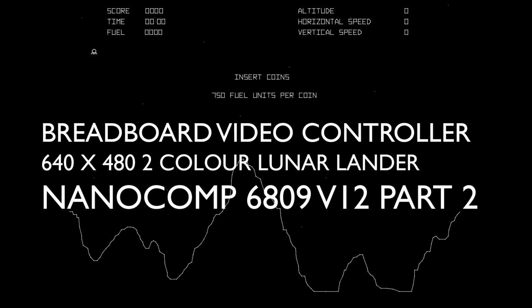I've got an analog joystick which I'd like to use for controlling the lander. The keys aren't particularly easy to use for it, so particularly the keypad on the Nanocomp is a bit clunky. So I'm going to try and design a circuit to convert the analog XY signals from the joystick into digital signals for up, down, left and right. And then what we'll be doing is trying to put that together in the final version of the program and see if we can make a half reasonable Lunar Lander game using the 6809 and our VGA graphics controller card.